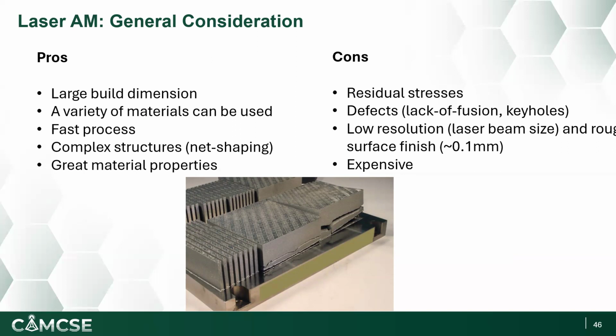Most often they may not degrade your tensile or compressive properties too much, but they may play a key role in the fatigue properties of many structural components, right? And we also need to keep in mind that because the laser has a beam size of about a few hundred microns, we have a limitation in terms of resolution.